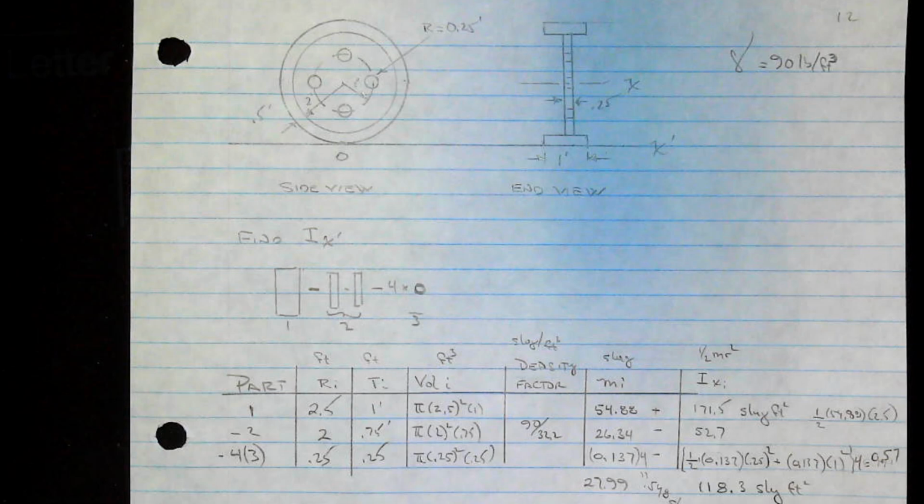They're all about the same axis. Whether they're on different sides or not, the thickness, I just doubled it. So I'm going to deal with both of these pieces. You see how I had two and I kind of grouped them together here? I'm going to deal with them both at the same time. Their combined thickness is 0.75. So knowing that, the volume is pi r squared, pi 2 squared, thickness 0.75, times our 90 over 32.2, we get 26.34 slugs.